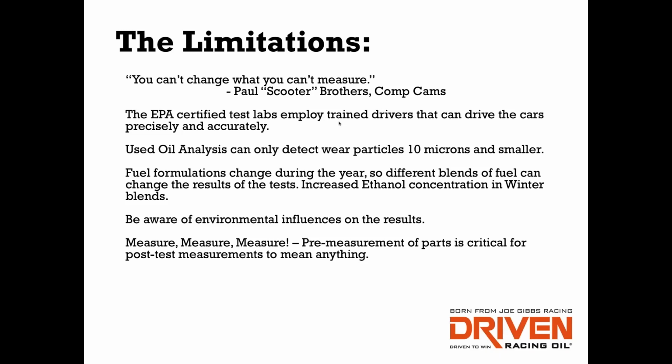Other things we came across: fuel formulations change throughout the year. If you put the same engine back up on the dyno here and there, especially with pump fuels, the ethanol content changes seasonally. There tends to be more ethanol in the winter, less in the summer. The amount of ethanol changes the amount of oxygen in the fuel, which changes the air-fuel ratio.